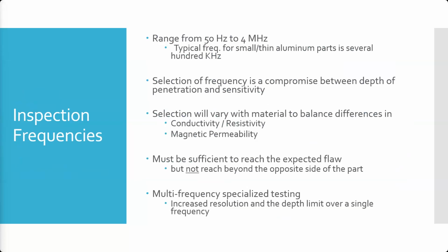So this one may not be readable anymore. I might have to look at my cheat sheet. This is 500 hertz to 30 kilohertz. Right? And then this one, remember, is even bigger. This biggest encircling probe is 100 hertz to 1 kilohertz, right? So you can see lowest frequency, medium frequency, high frequency. This is for your steel bolts. That's why it's such a big probe. It runs at a very low frequency to try to get that better depth of penetration.